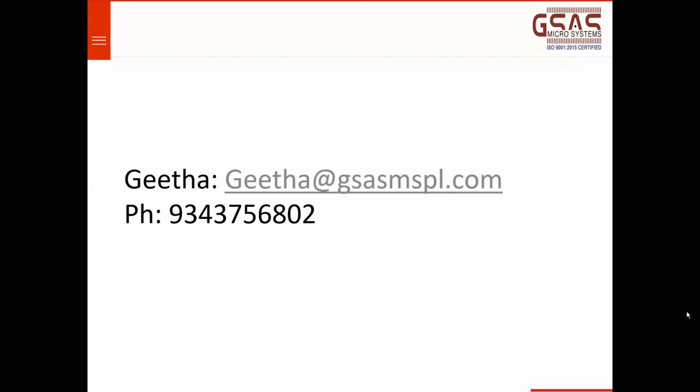Oh, okay. Fine. That was my question actually. I think it is related to this, which is not available yet. At least I cannot see it on my laptop, because maybe that processor has not been simulated by ARM yet. If you're not seeing simulation, you have to see what device you're using, and if any simulation support was provided by Keil, then you have to download the legacy pack.